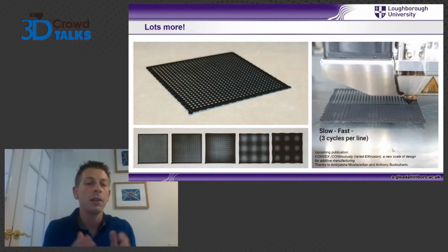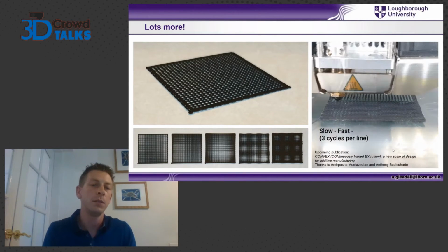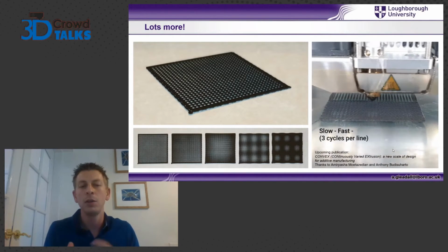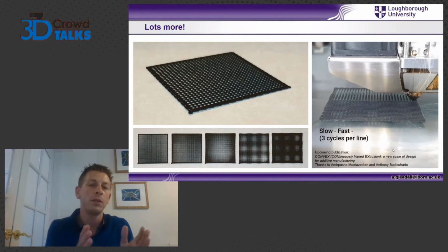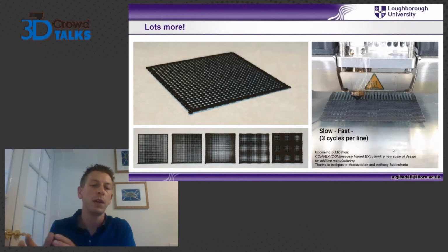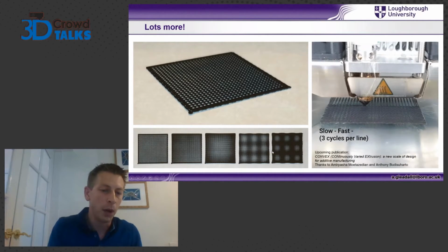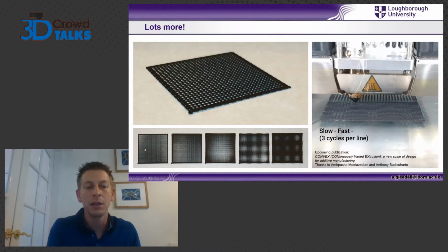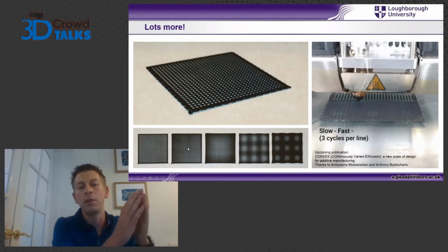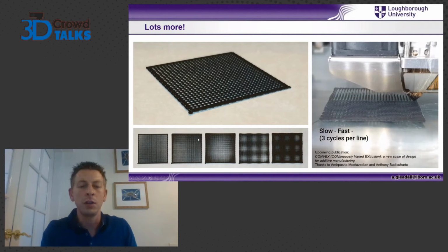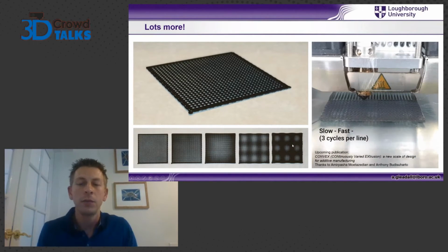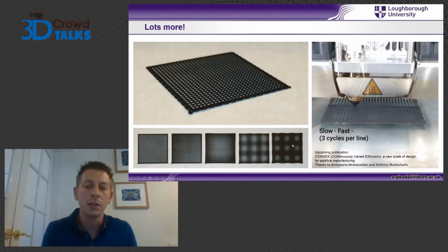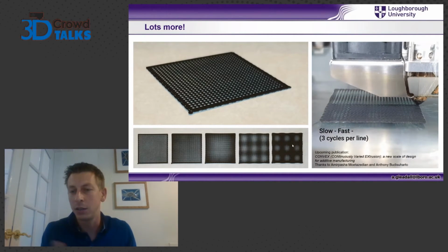You can potentially vary that by varying the spacing between filaments and that sort of thing, but you can't really control it very well. That would just gradually vary the pore size. Like the bottom left image is showing a perfectly neat grid. The second one is showing a kind of gradient, but what we're showing on the other three is, again, sort of sinusoidal changes, and we achieve those by changing the speed.